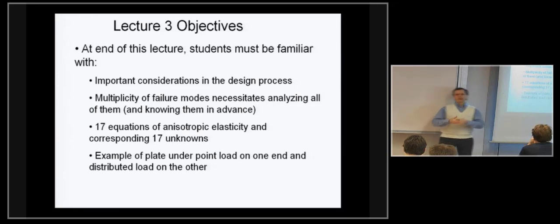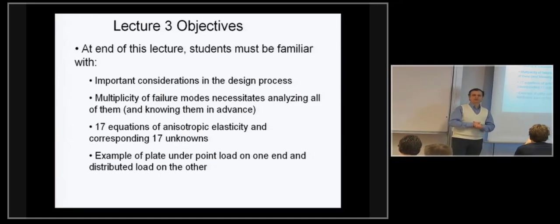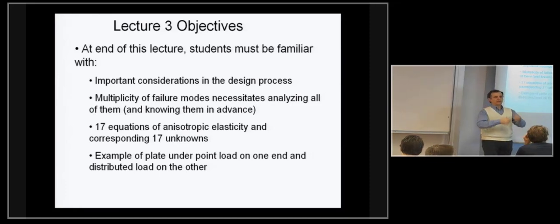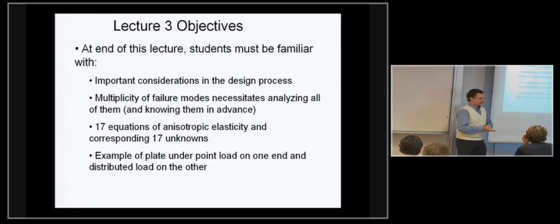Based on those and applied loads, you can calculate strains and curvatures. Then we talked about failure criteria, which is the next step. You use all these strains and stresses to try to predict failure, because ultimately you want to design these structures for lower weight or for a bunch of other attributes that we will be covering today briefly.